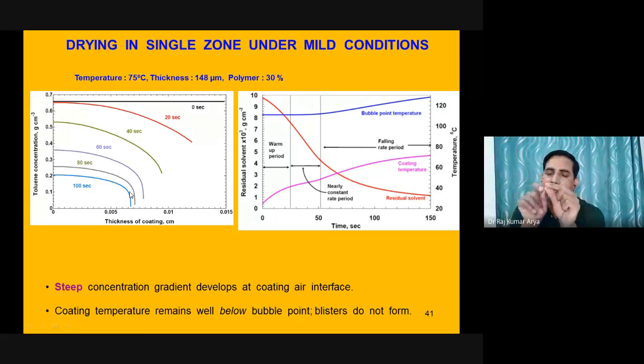So if the element size is bigger here, I will miss this particular picture. I cannot capture it. So in this section, nearly the top surface, I need more and more elements so that I can capture the steep concentration profile. And on the bottom side, I just want a bigger one, because here there is no huge change. It is slowly changing.